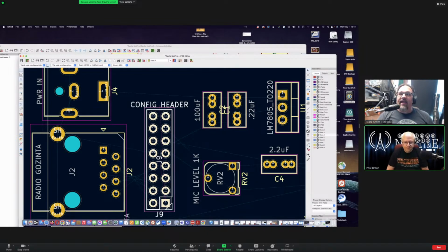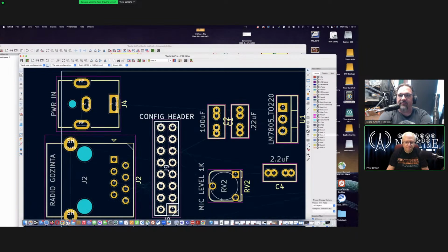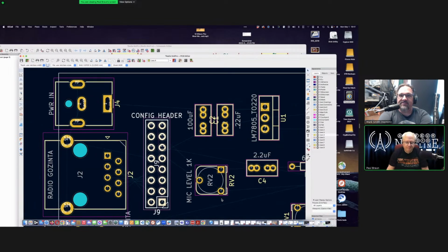Okay, so look at how these are numbered. It goes across the board first, row first, then column, not column first, then row. Yeah. That is a typical numbering for a pin header. So I would rather keep that numbering for the pin header there and then switch the schematic to match the pin header.